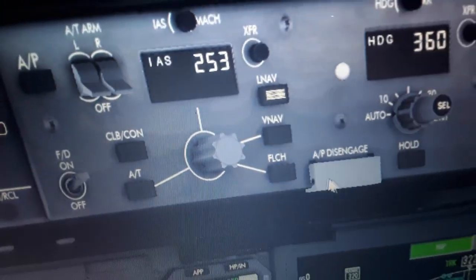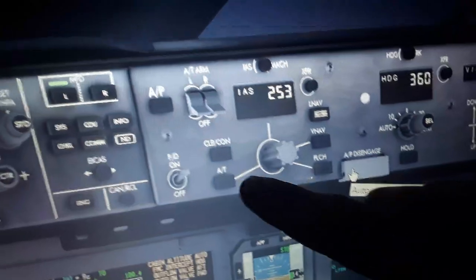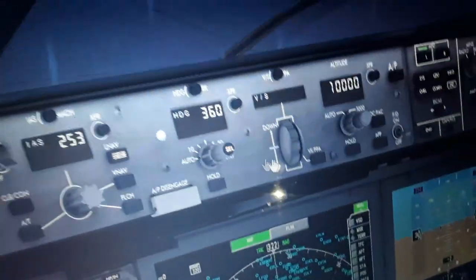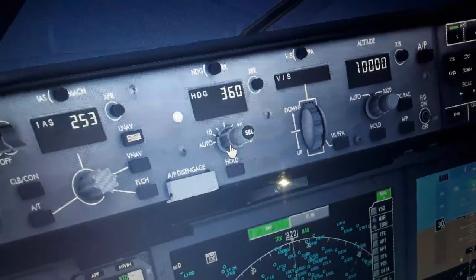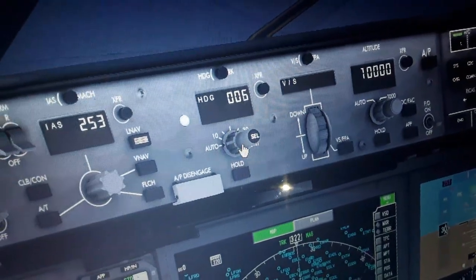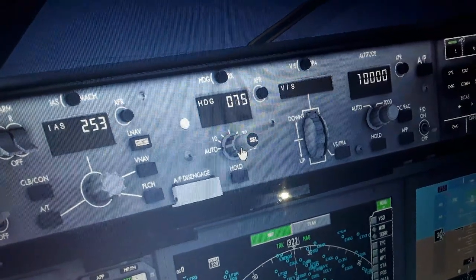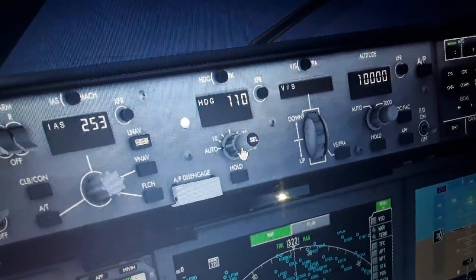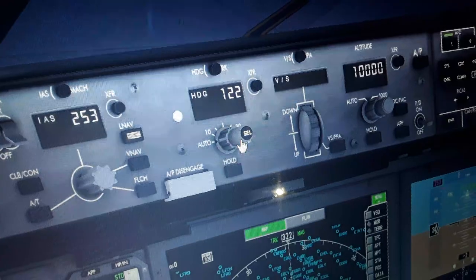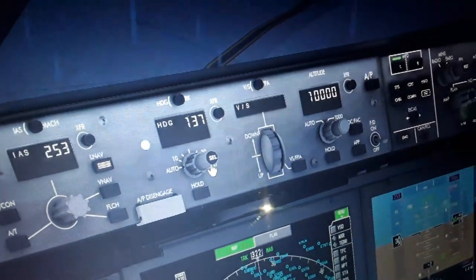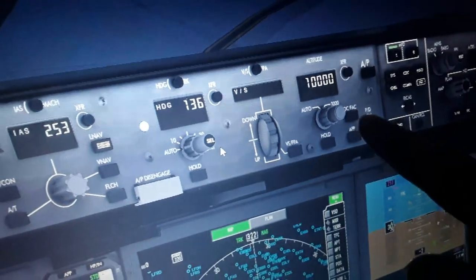Autopilot disengage, you see here, pull out. Flight level change, so the throttle climb continues. We're going to use the magnetic north pole heading of the airport, the bank angle in flight also. So we select heading 136 degrees. You will see everything displayed later in the autopilot flight director system panel. 136 degrees. VOR localizer, approach for autoland.